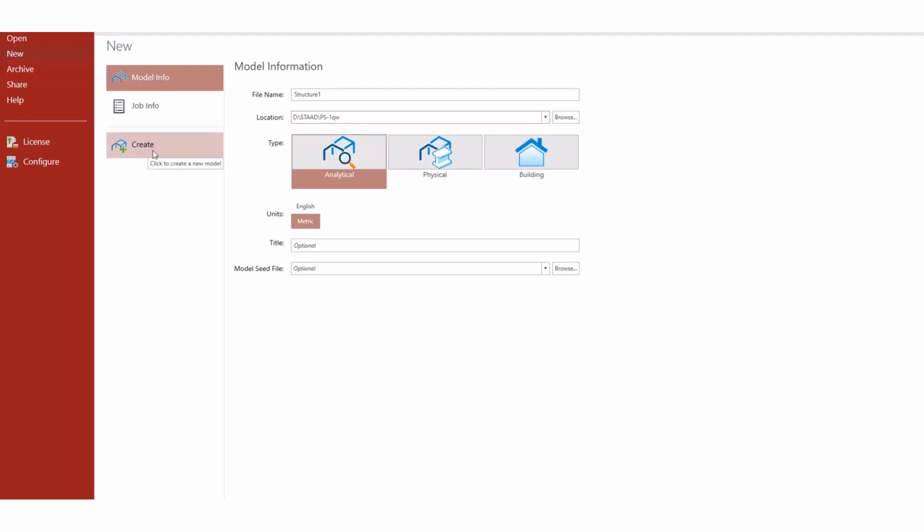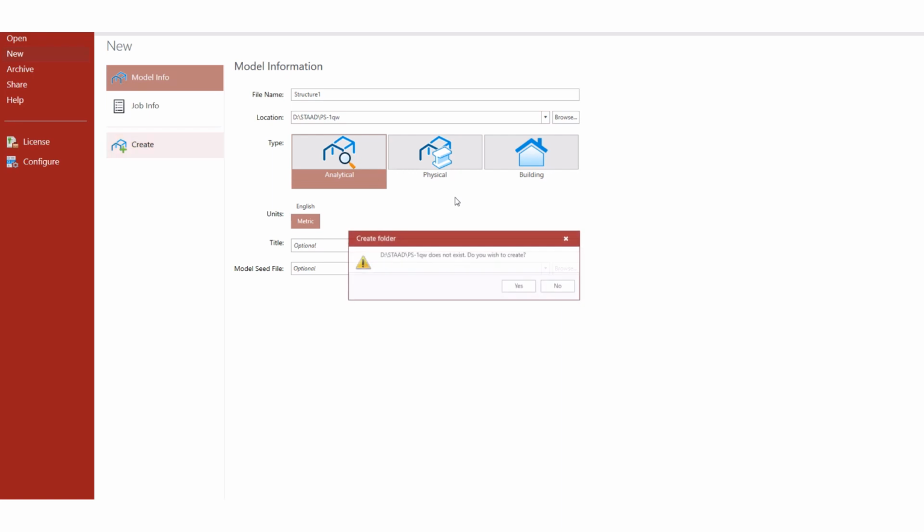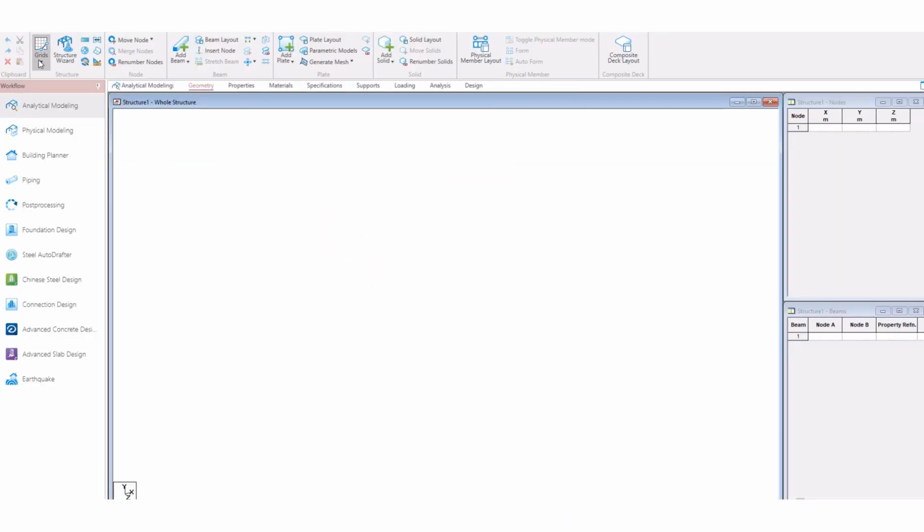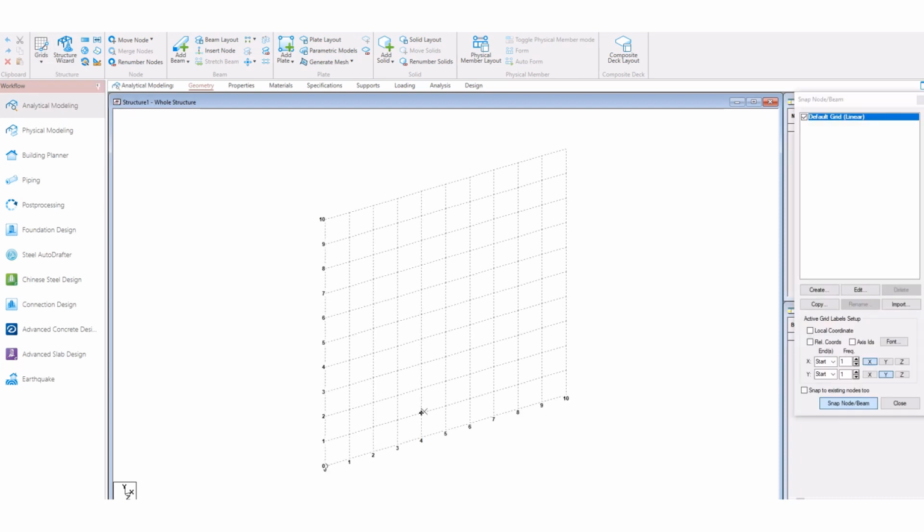Let's create this model. We want to create, and go to grids, beam grid. Let us make one frame, 5 meter, and this is 1 meter distance, so one small frame. Let us give the load here and fix the support here. How it behaves we will see.